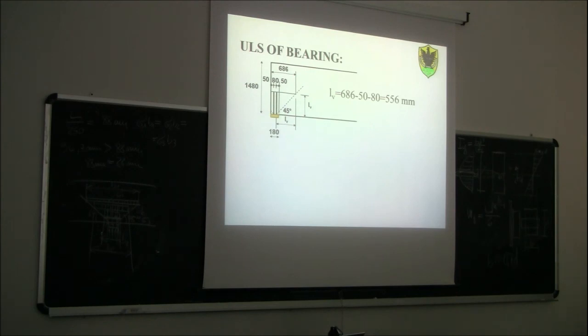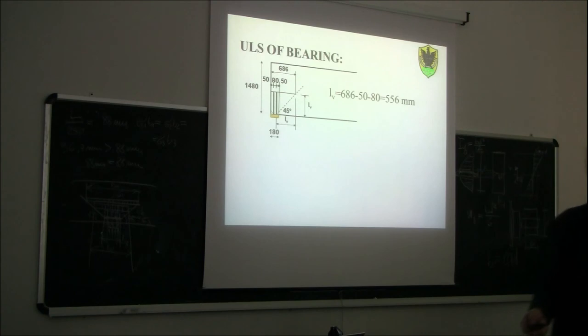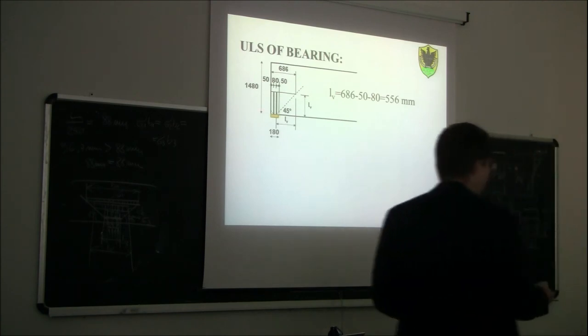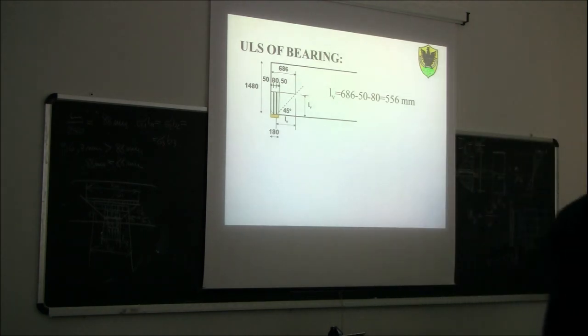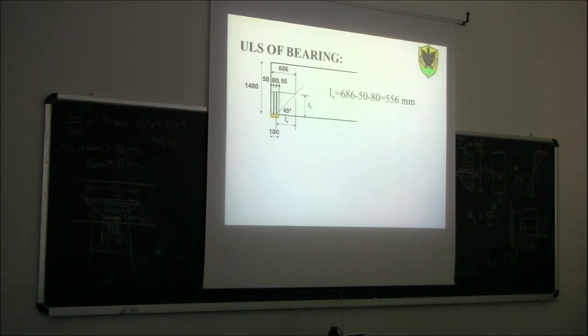Later on, when we understand how to calculate the strength of a screw connection, we'll also be able to make sure that those screws are sufficiently strong to transfer the whole load. Because if you think about it, suppose you put a very slender screw inside to transfer a very huge load. What could happen? You have a very strong restraint reaction, you put only one very long but very slender screw. What could happen if the load is too high and the screw is too small?